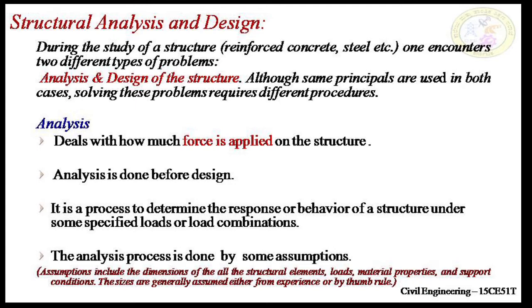Analysis is a process to determine the response or behavior of the structure under some specified load or load combination. The analysis process is done with some assumptions. The assumptions include dimensions of all structural elements, loads, material properties, support conditions. The sizes are generally assumed either by experience or by thumb rule.